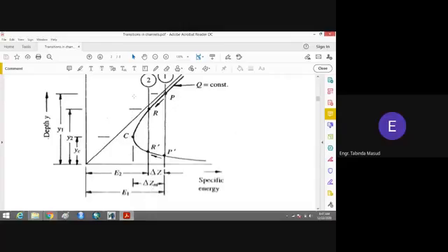Section 2.2 will remain constant over here, but section 1.1 will start moving towards the upstream side. And that will be the damming action. That will be the case which I have already shown you in your Franzini book: if you further increase the height of the hump, then there will be a rise of water level at the upstream side.